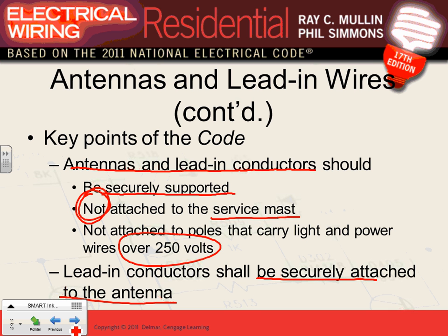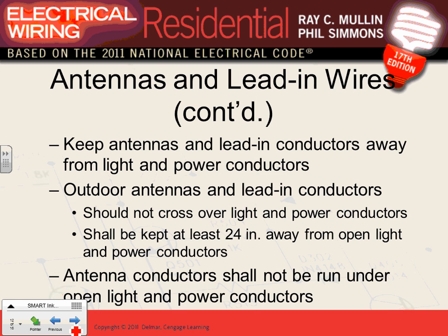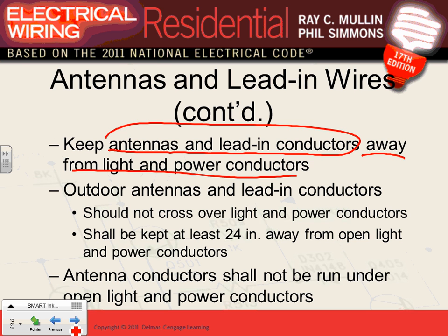All these low voltage articles, it talks about work. It has to be done in a neat and workmanlike manner, because we just got tired of people throwing all these coaxial cable wherever it goes, right? Keep antennas and lead-in conductors that you have away from the power and light. That's a big deal. Outdoor, so again, separate all these systems, guys, all these systems from the power. You can see they keep repeating themselves.